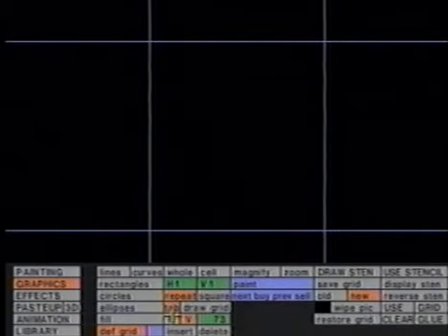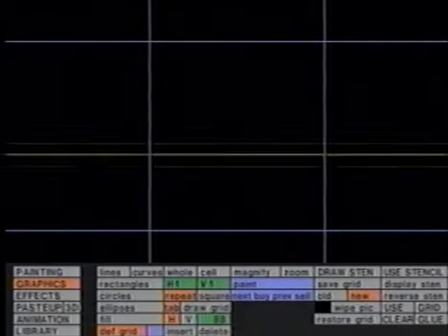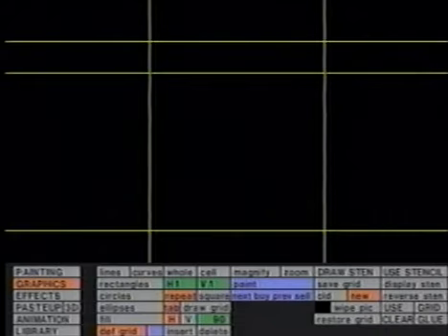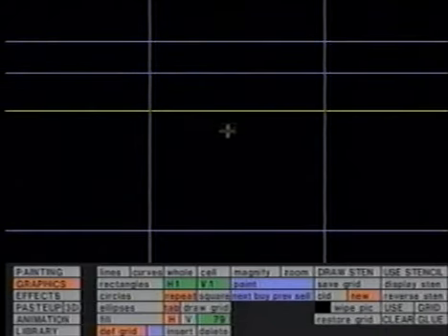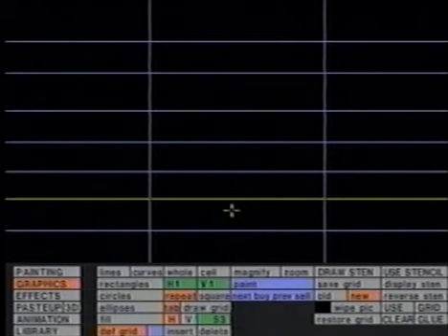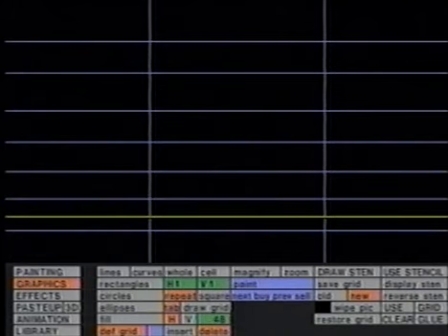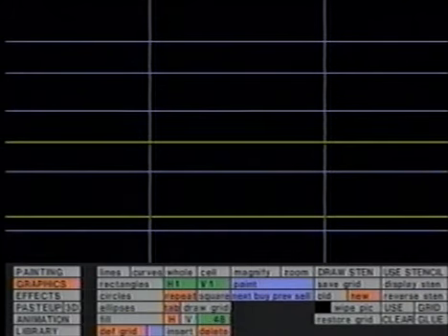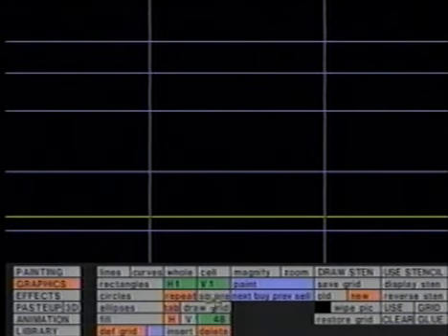With Tab and H on, a tab line is added each time the pen is tapped in the picture. Using Delete, the tabs can be removed. Note that passing the pen over the picture selects the tabs, indicated by their turning yellow.